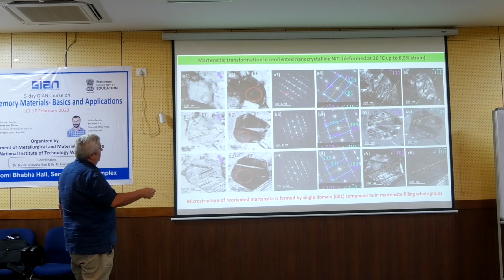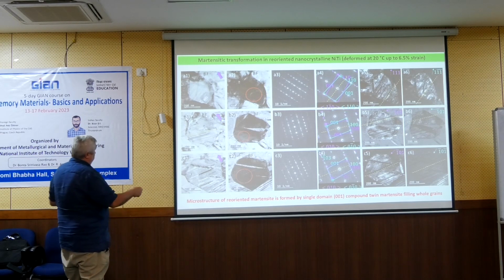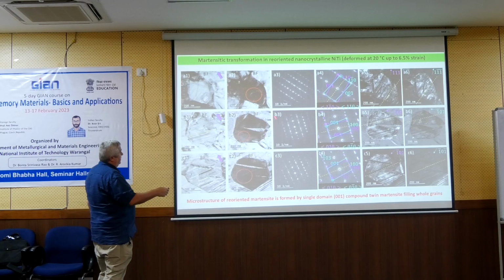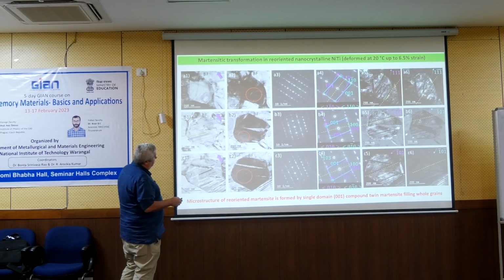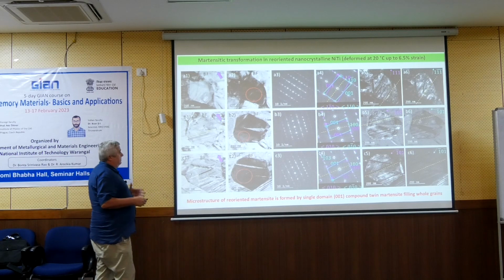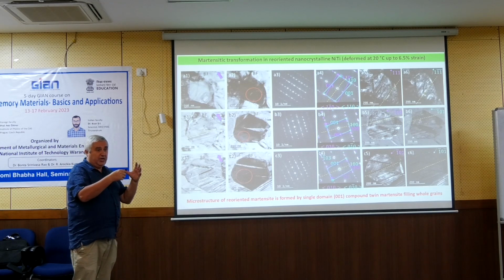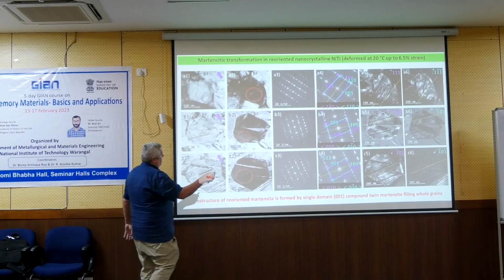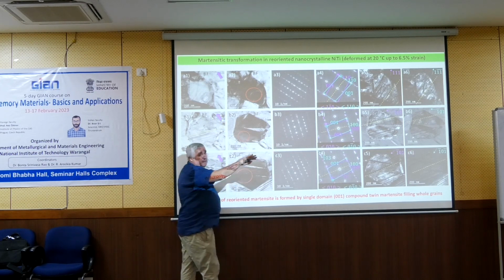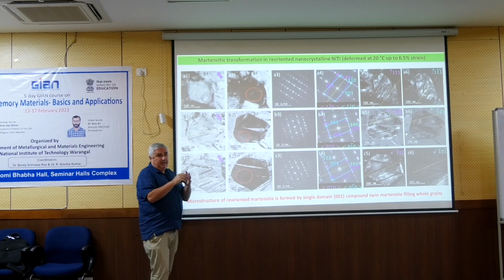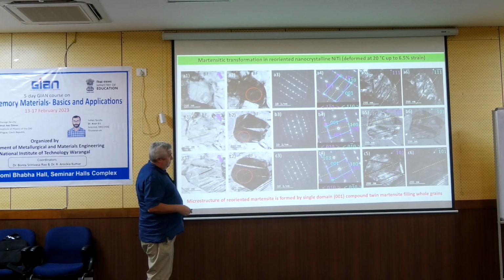This is the 001 compound twin, and this compound twin fills the complete domain. Some grains, if you look into them, will have some kind of relic bands, but one can understand this is after reorientation. Before there was a jungle, and these relic domains, if we deform a little bit more, will disappear. They were here before, and during the reorientation the other domains, because they provided less strain, disappeared, and you end up with such a structure.